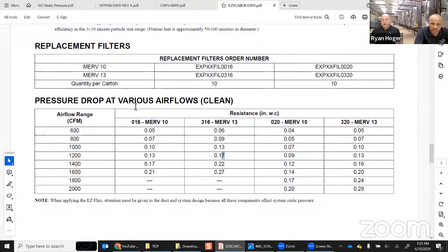And along with that, if you have a real dirty filter and a dirty blower, but yet your evaporator is clean, you have a secondary heat exchanger on a 90% furnace, which also gets plugged up. So there's a number of things that cause static issues, limit issues, and this is a problem every year for tech support calls. Limits are constant calls, and usually no one could answer the question: what the gas pressure is, what the static is, what your temperature rise.